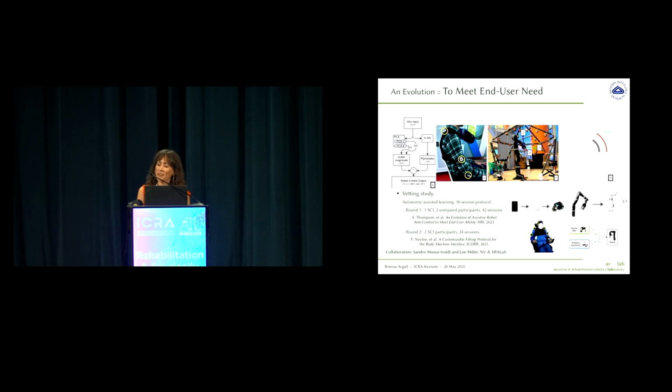And then we also had to update our actual study protocol, so the progression of our study sessions and what role the robotics autonomy was playing in those sessions. There were a number of reasons for doing this, and we made a number of changes. I don't have the time to go through all of them, but I will highlight that one of the reasons was that we had a false assumption: we presumed that lower dimensional robot control would be easier than higher dimensional robot control. The reason that ended up being false is that teleoperating this robot arm is very prone to getting stuck in singularities, and it's really hard to get out of the singularities if you can't wiggle your way out in all the control dimensions.